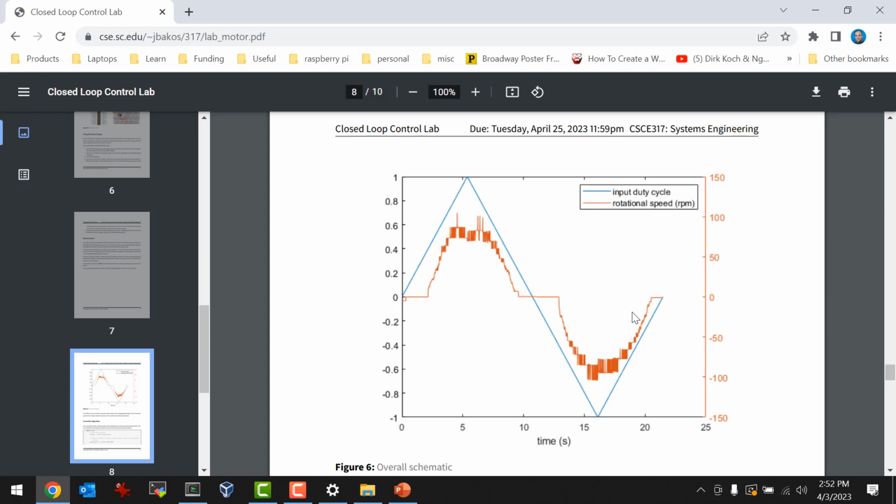from that to about 60% duty cycle, it kind of increases, but then it maxes out at 60%. So if you go from 60% to 100%, it makes like no difference, right? So you have pretty much a useful range there of only about 0.4 to 0.6 on the duty cycle. It's weird, but that's okay because the controller hopefully will account for that, right?